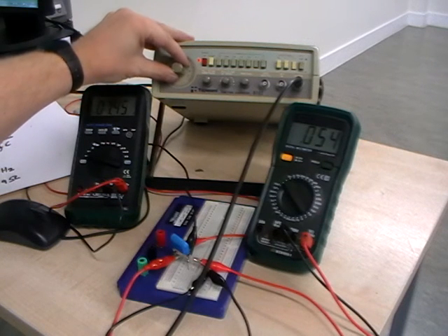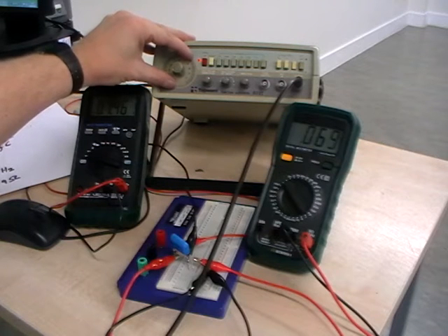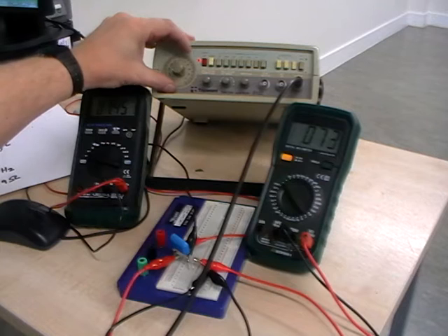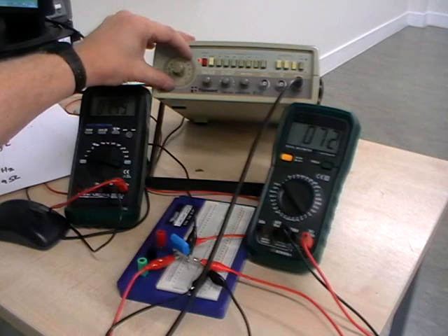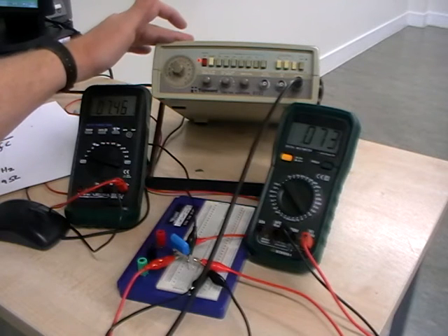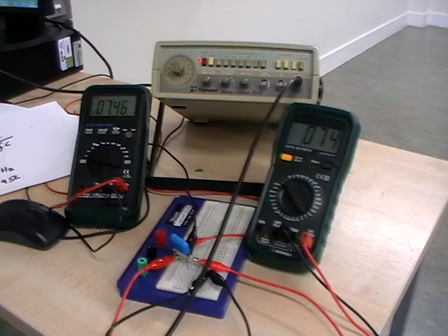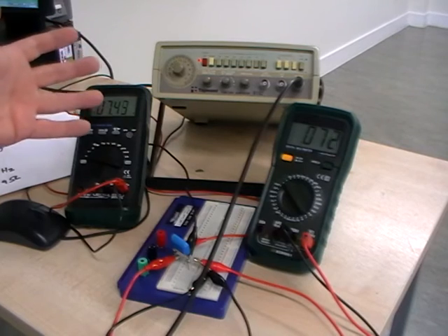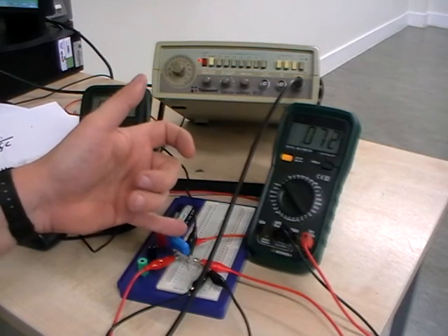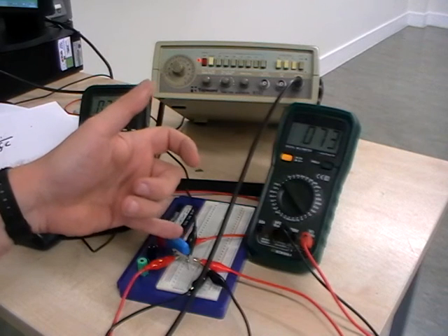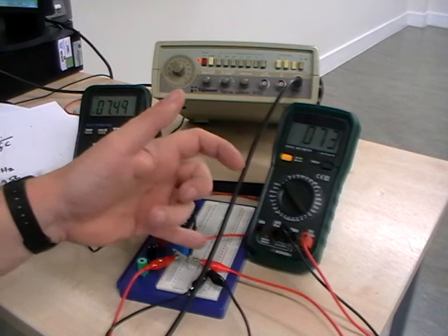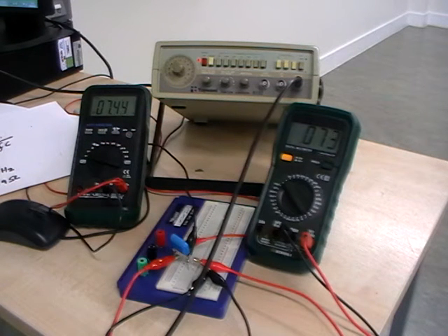Let's try and see whether we can get a factor of 100. So when we go to about, again, it's a signal generator, I'm not sure how precise it is with the frequency. But when we go to about 12 hertz, we've got a factor of about 100. So that means times 10 would be 1,500 ohms. On that one, times 100 would be 15,000 ohms. So we've got about 15K now in our reactance, in our capacitor, and we've got 150 ohms in our resistor, which again doesn't change, but we can therefore compare one with the other. I hope I got those figures right. I'm just doing it out of the top of my head.